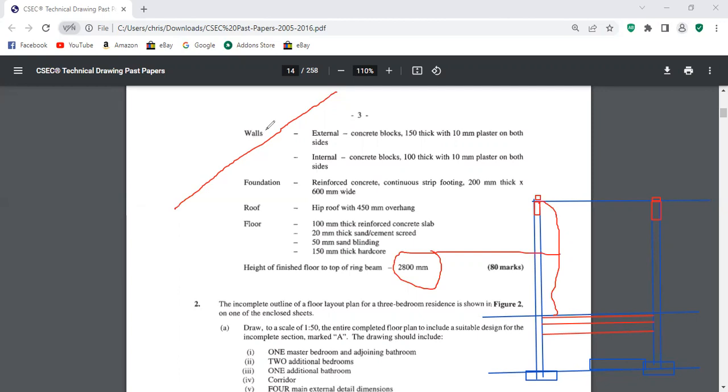I would draw the rafter here. Let's sketch this first and then we draw it. So I would then draw it here, then left click and then drag it into here. Question, how would you go about generating the overhang? Yeah, so let me use a straight line for this.